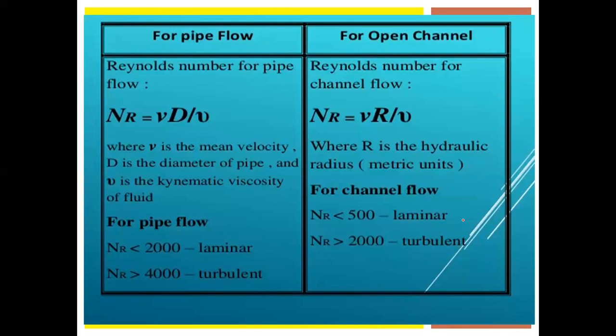Coming to the Reynolds number, we apply it to pipe flow as well as open channel flow. For pipe flow, the Reynolds number NR is equal to VD divided by ν, where V is the mean velocity, D is the diameter of the pipe, and ν is the kinematic viscosity of the fluid.